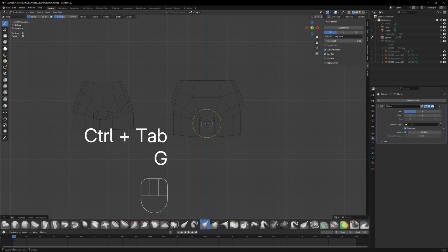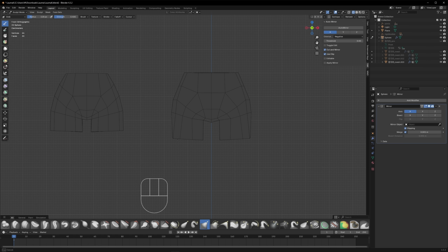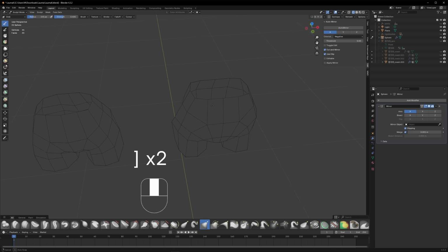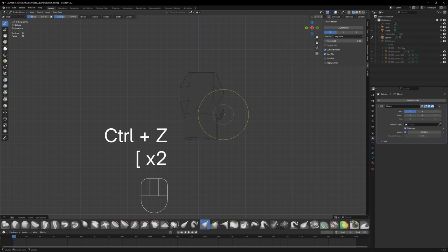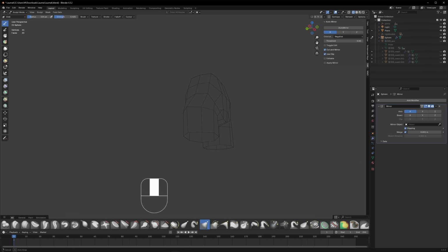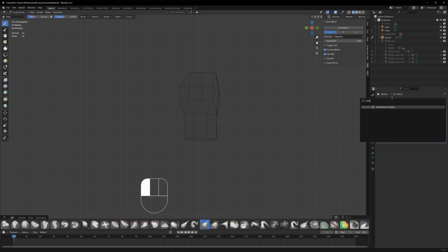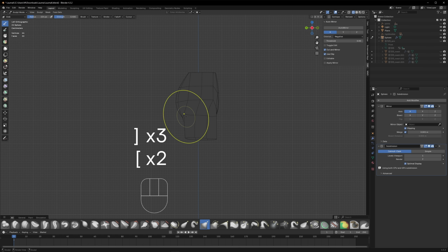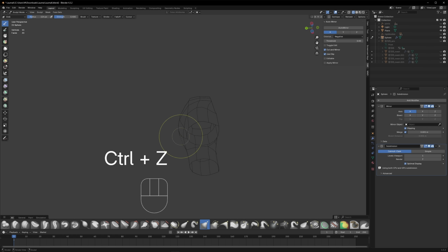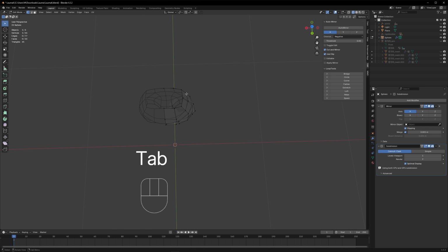But obviously the proportions and curves are not the same. So we go into sculpt mode and move these points around using the grab tool as kind of like a glorified proportional editing tool. Since it's a low poly structure right now, there's not much that can go wrong here. And all I have to do is push in the front and push out the back. And this is the point where you add the subdivision surface modifier. Now it'll be a lot easier to visualize the curves. All we really need to do at this point is to capture the basic silhouette of the pelvis. We can add the finer details later.